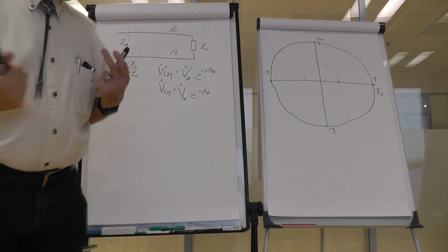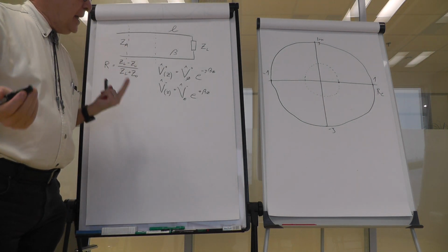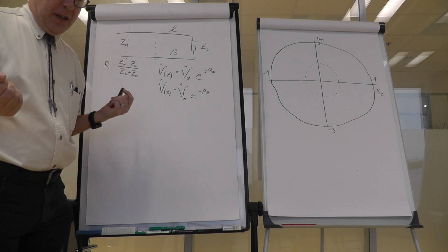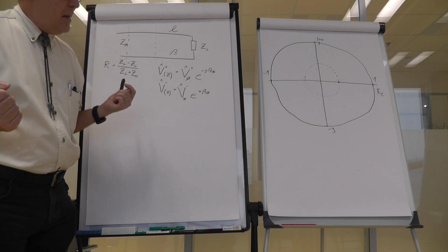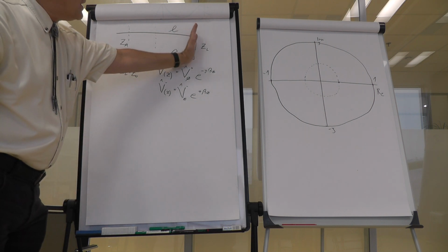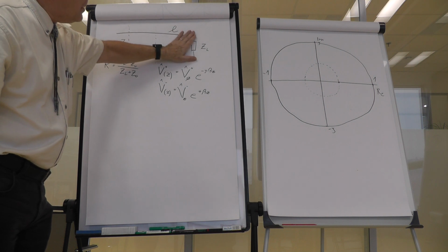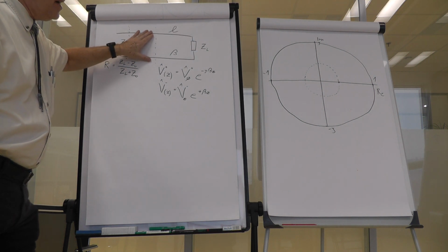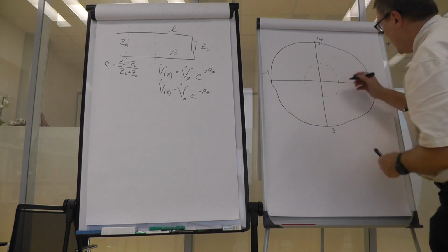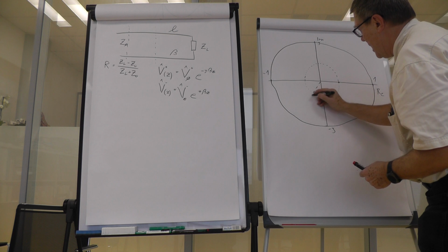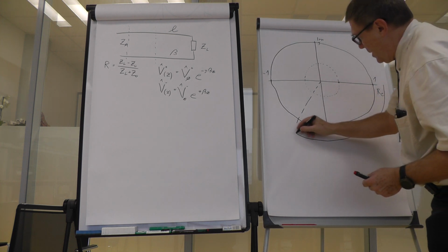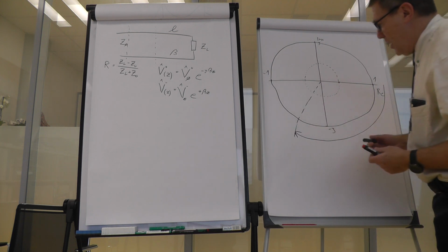Now we can easily get a reflection coefficient with any phase just by putting a real resistor on the end and moving a little bit, moving properly. So if we would like to have this angle, we would just have to put the resistor and move this long.